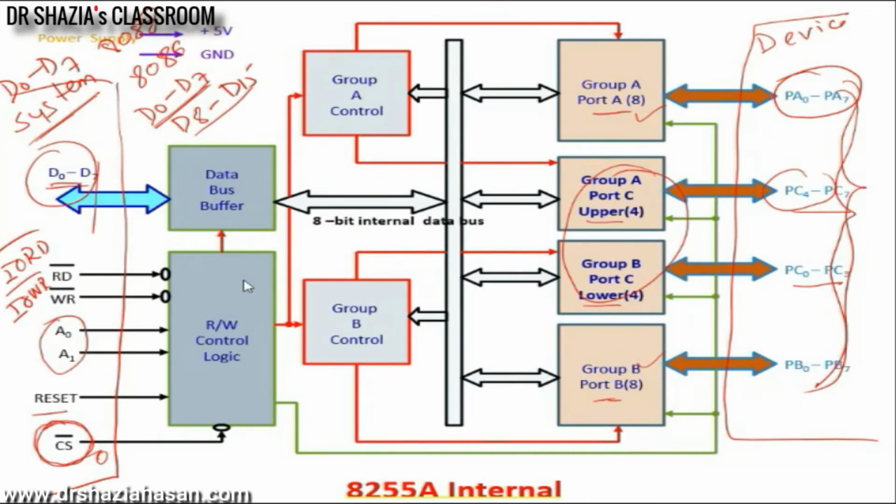So one IO device can transfer 8 bits of data, and that D0 to D7 bus is either connected to the lower data bus of the 8086 processor or to the higher data bus. So at a time you are using either even addresses or odd addresses, if it is an 8086 processor and your device is an 8-bit device.